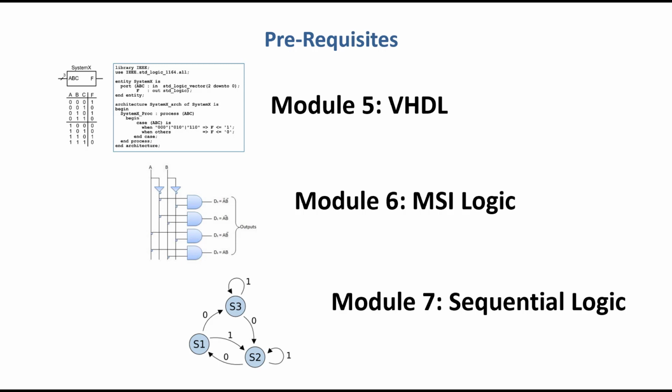So if somebody said build a multiplexer, all you really need to know is how a multiplexer is supposed to work, create the truth table, and then synthesize the logic using a Karnaugh map. Or you could, if you knew how it worked, describe the multiplexer in VHDL and synthesize it using an automated CAD tool. Finally, we wrapped up with sequential logic.